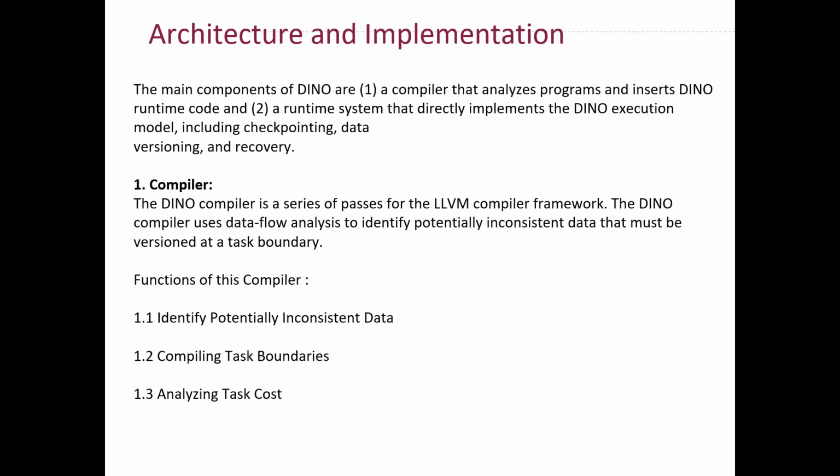So in that sense, the prototype assumes that no non-volatile accesses are happening before the program's first task boundary. And these task boundaries are points at which execution might resume if a reboot follows the non-volatile store, which we initially defined as S. So it doesn't follow S's execution.